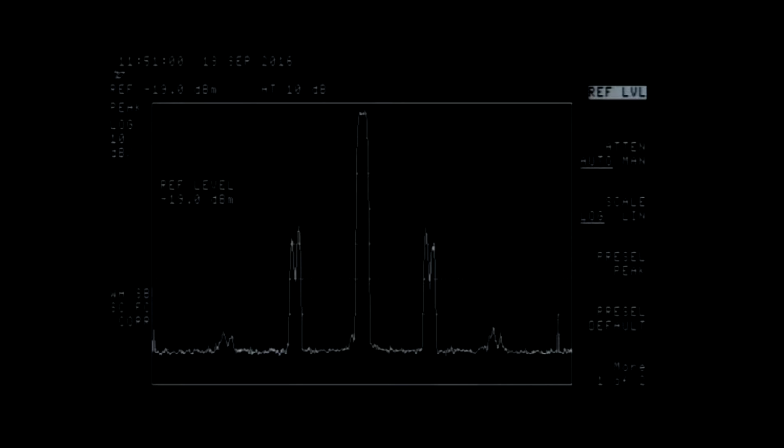Currently with DVB-S2 I haven't added all the required interpolators and filtering for the reduced bandwidth modes, so the picture above shows you why you shouldn't operate the software below 2 megasymbols at the moment. I'll do a comparison with DVB-S software, which does actually have the correct filtering, so stand by.